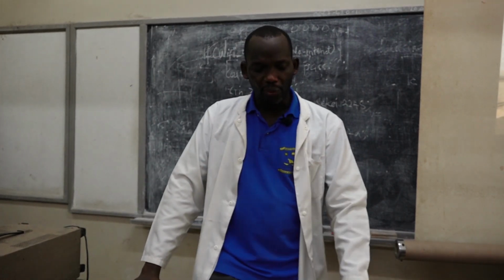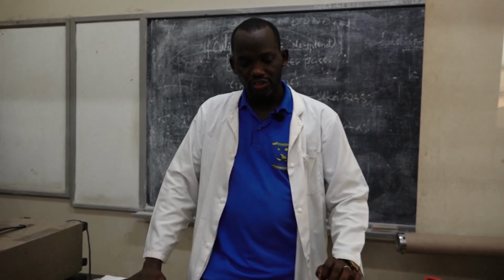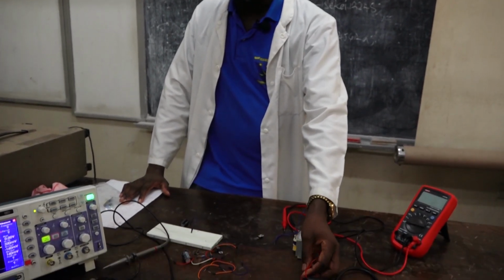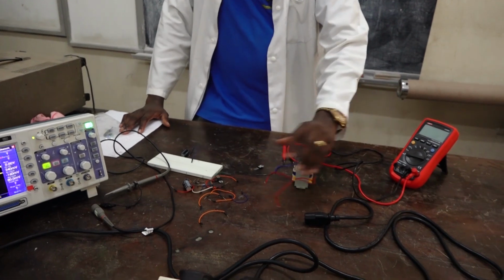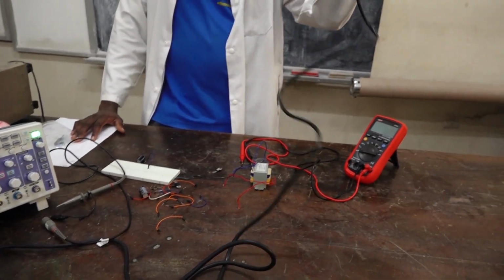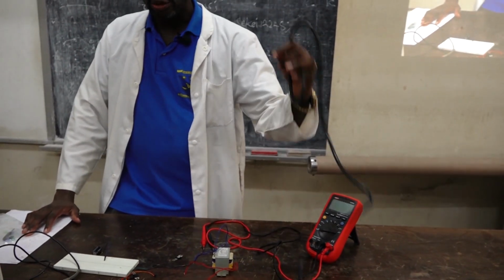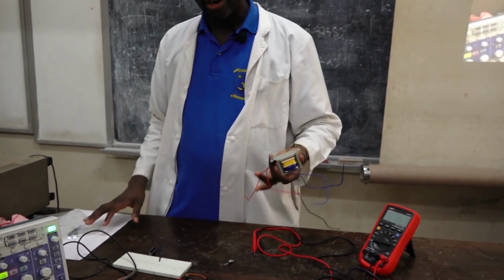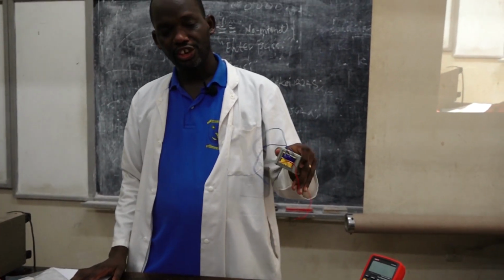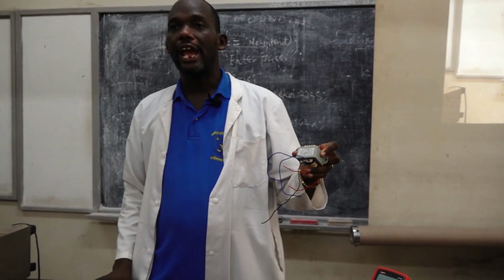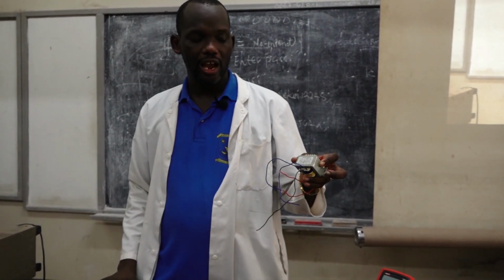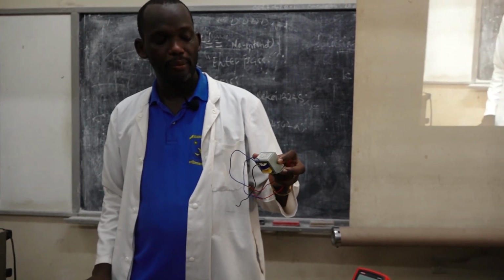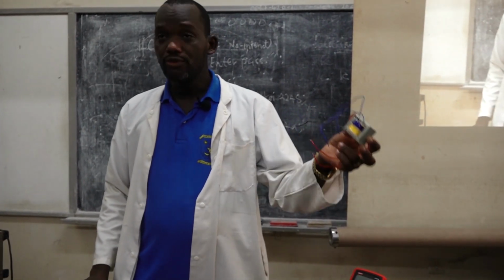The first thing I want to introduce to you is the materials and the instruments that we are going to use for this workshop. Firstly, we have a power cable, where we are going to take power from the main AC. Then this is the step-down transformer, which can take 220 volt and provide 60 volt if you use it as a non-center-tapped step-down transformer, or it can provide 12 volt.